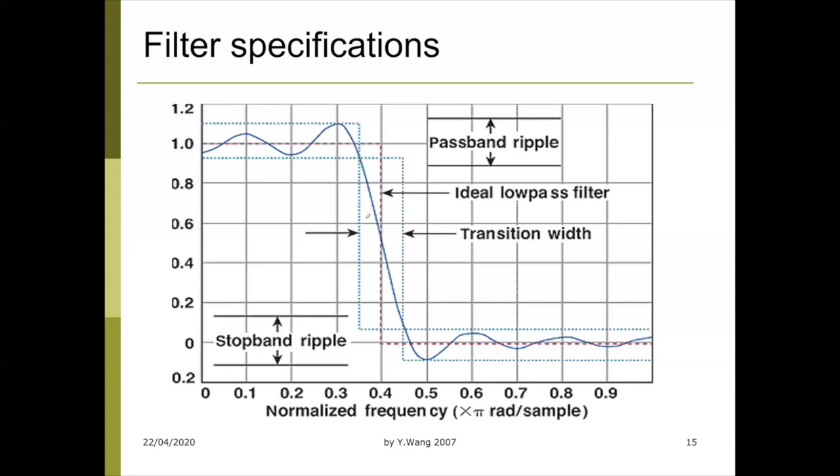We have a transition band. An analog system has a transition band, which is very natural. You can design a very steep digital filter, but your digital filter probably will not be able to realize it. For example, you need a 1,000 or even 10,000 or millions long filter to be able to have a very, very sharp digital filter.